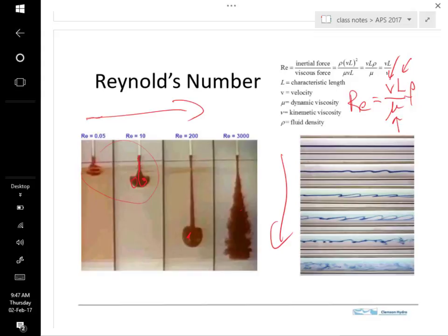Yeah, TJ. Are there supposed to be two V's in the equation for velocity and kinematic viscosity, so like another variable I could use? What's that? Is there another variable I could use for kinematic viscosity, or is that meant to be two V's? Yeah, so this version of it, that's kinematic viscosity, and that's velocity. Okay. So kinematic viscosity is these two terms here. So the kinematic viscosity is equal to the dynamic viscosity divided by the density.